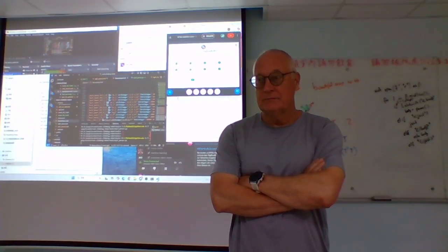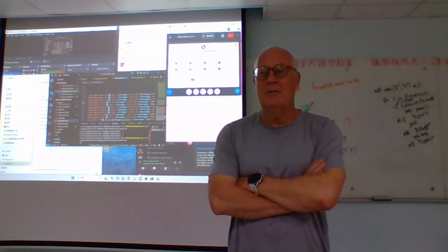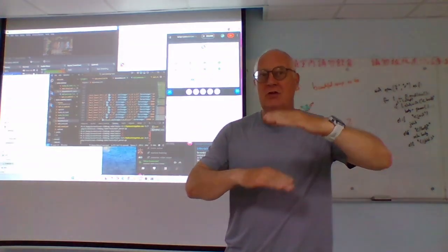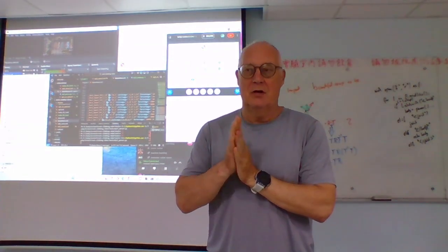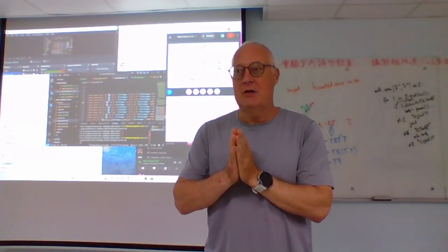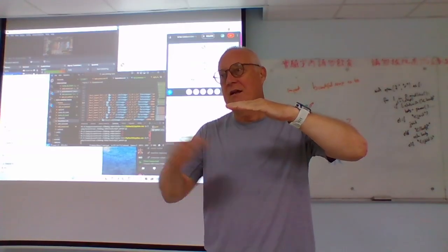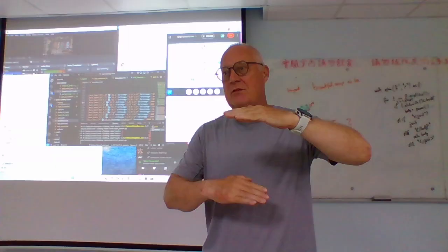But is there a way of making the XML file dynamic? Otherwise, whenever we change something, we have to open the XML file and type in the thing? So usually you need to have an XML file to define your simulation environments because it needs to pre-calculate a ton of things to be fast enough.